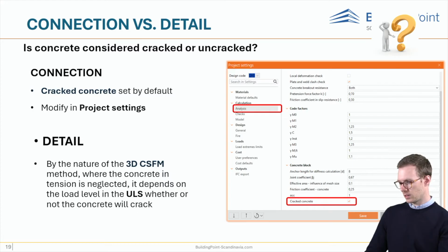The last question to clarify: is the concrete considered cracked or uncracked? In the connection application, you as a user can decide if you want to consider the concrete cracked or not. You can do that in the project settings, but in the detail application, the concrete in tension is neglected, basically. So it depends on the load if the concrete is cracked or not. The application will calculate it for you.